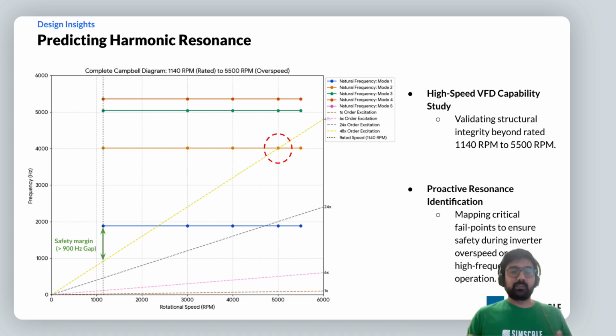While designing, we can consider that as the boundary of the motor, or if this is a high frequency motor application, you would need to actually skip this particular RPM and frequency combination to make sure the motor's life is longer and doesn't go under any structural damage.